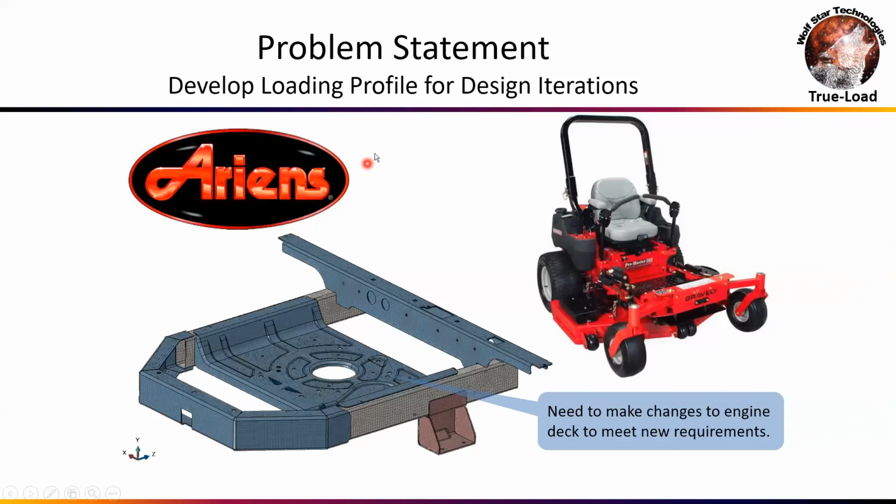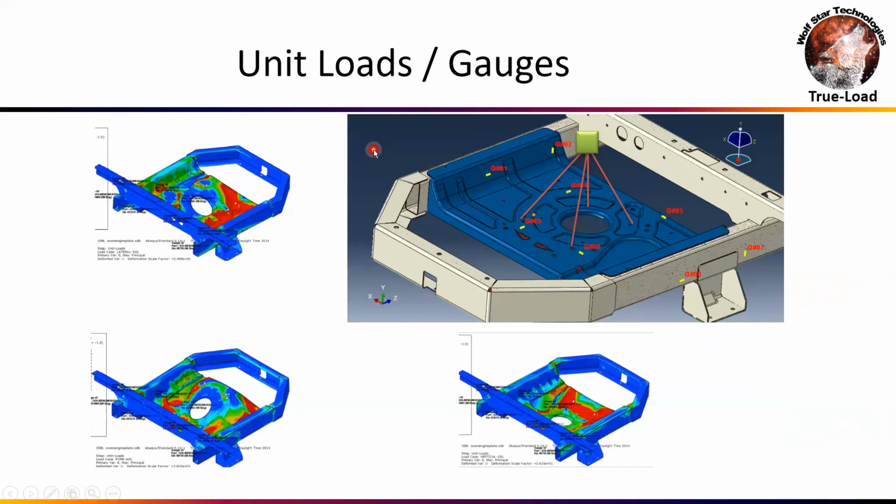And so working with the engineers there, we decided to treat this as a base excitation problem. So what we did is we modeled the engine and transmission as a lump mass, tied that into the structure here.